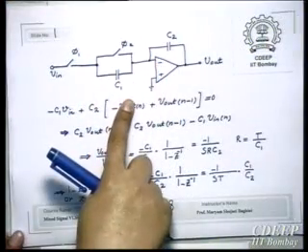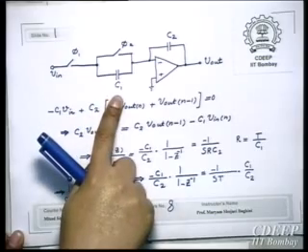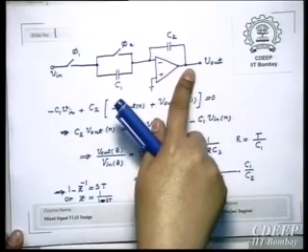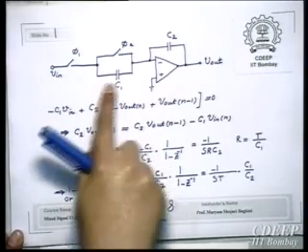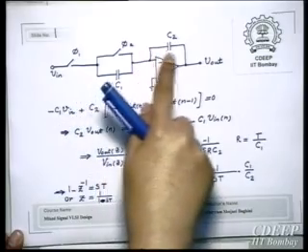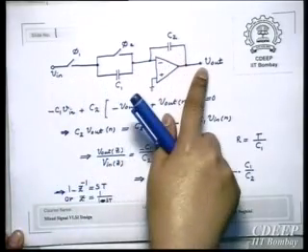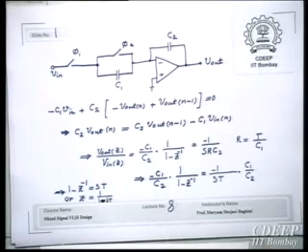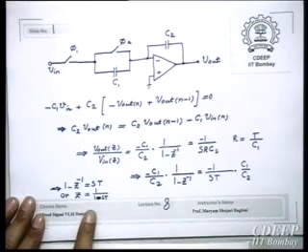This circuit does that. So in phase phi 1, as you notice, C1 gets charged, and at the same time C2 also will get charged. Because the current which flows across terminals in C1, it should flow through C2. There is no other way, right? Therefore, we are charging C1 and C2 simultaneously. Then in phase phi 2 only, we discharge C1. Therefore, now this will be backward Euler because there is no delay between output and input. And if you write relations, you will get backward Euler relation.